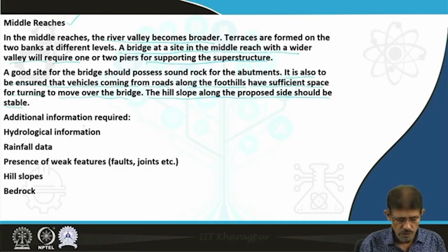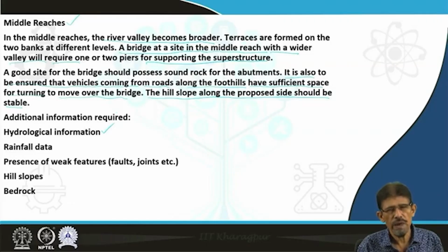In addition to this, we require information regarding the hydrological condition of the river, so that we can assess the flood chances, the rate of erosion as well as the flooding zone, etc. Then we need the rainfall, the presence of weak features below the soily layers and the condition of the bedrock.